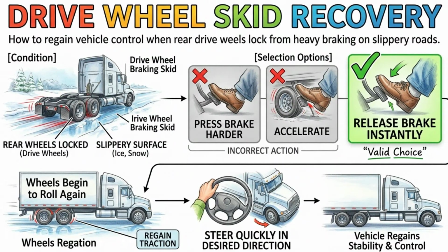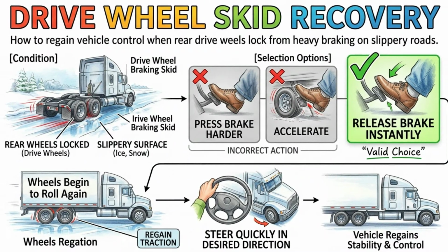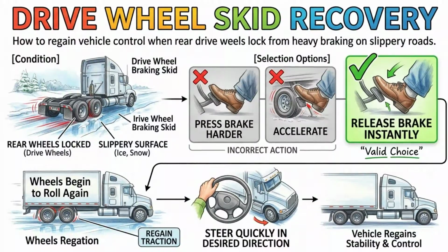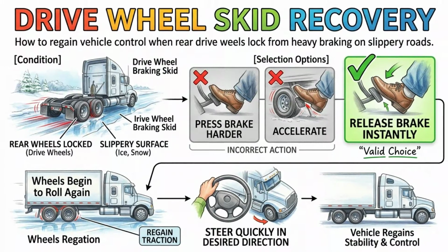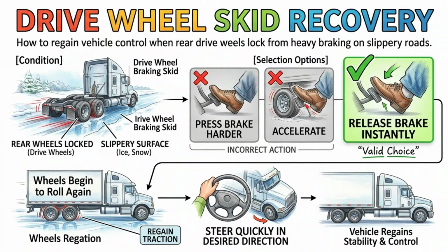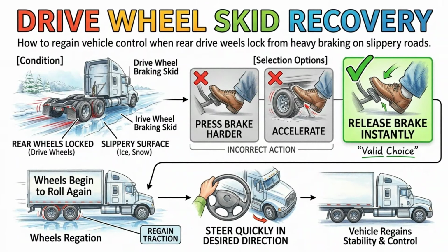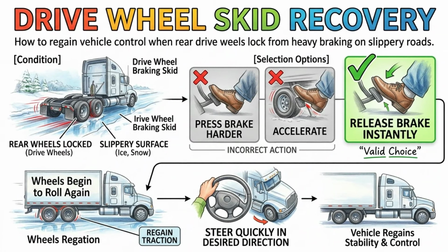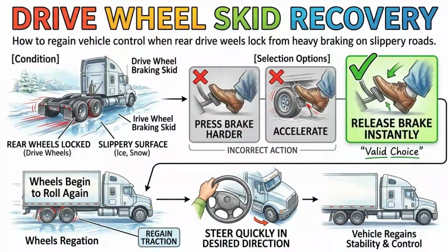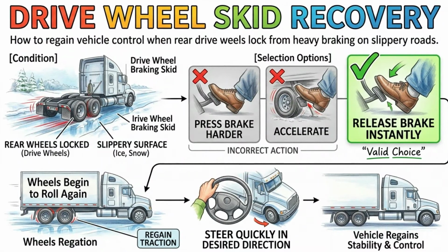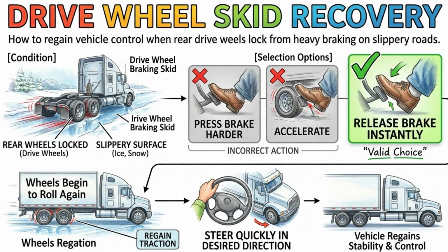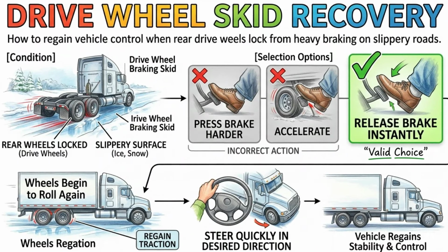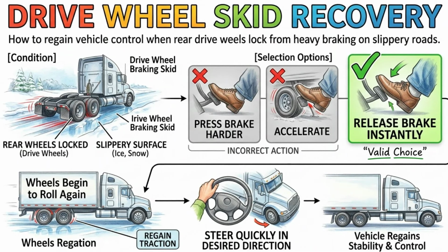Mountain driving requires intense speed management and a deep understanding of your vehicle capabilities. The single most important rule for driving down a steep grade is to select a safe speed that is not too fast for the weight of your load and the steepness of the hill. Once you select that safe speed, you must be in the proper low gear before starting your descent. You should then use the braking effect of your engine to maintain that speed. Relying primarily on your foot brake will cause the brakes to overheat, lose their stopping power, and fail completely.